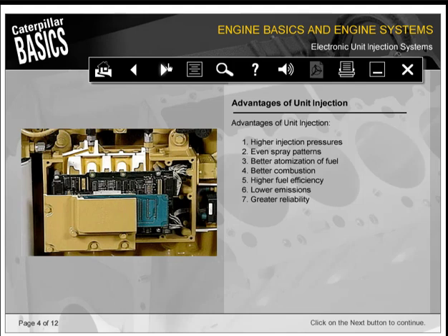The advantages of unit injection are higher injection pressures, even spray patterns, better atomization of fuel, better combustion, higher fuel efficiency, lower emissions, and greater reliability.